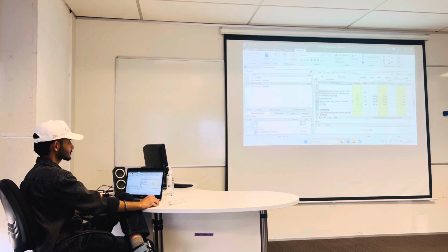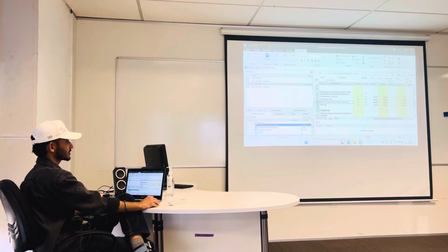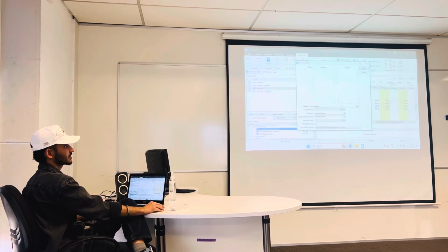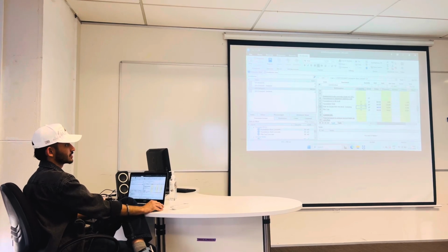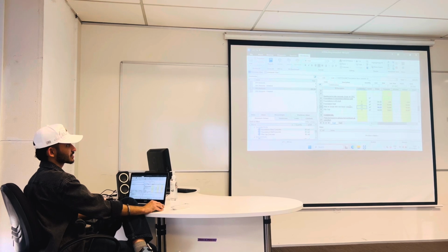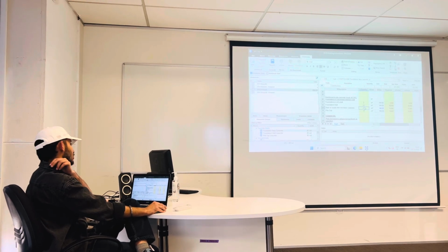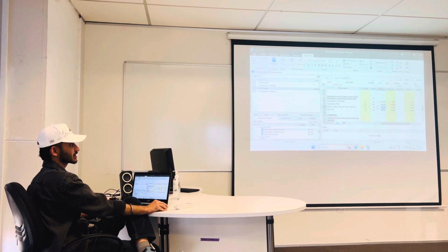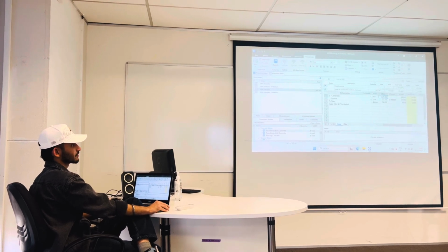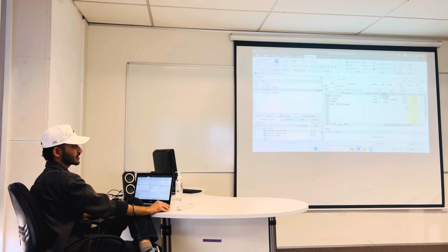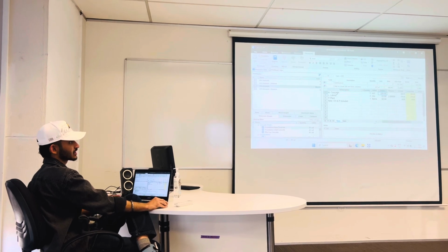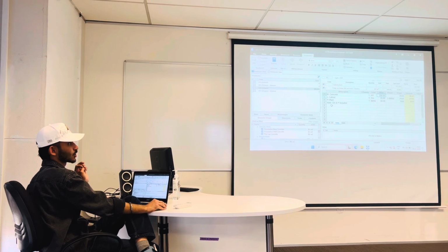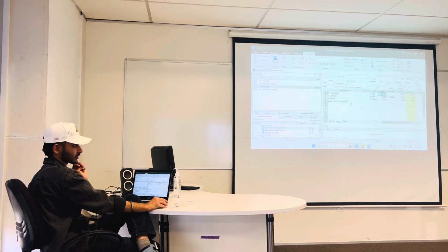So we have foundation base concrete. We will put the detail, drag and drop here and update. So the quantity of the grade, slab on grade for the concrete is 29 meter cube, and this is the rate calculated. When we double click on it, we can know how we calculated the unit rate. So we calculated the material, labor and the machinery prices along with the overhead and profit included.